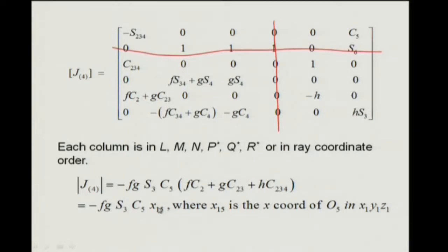So are these concepts reasonably okay? I can do it quickly, and when I eventually calculate the term, I am going to use the DH parameters and those matrices. But this tells me that I just need to evaluate this parameter x15 and I am in business. I do not have to do the rest. And remember that to do my forward kinematics, I will anyway have to multiply those matrices out. So it's not too much additional work. I am just using my knowledge of robotics to combine these things together.